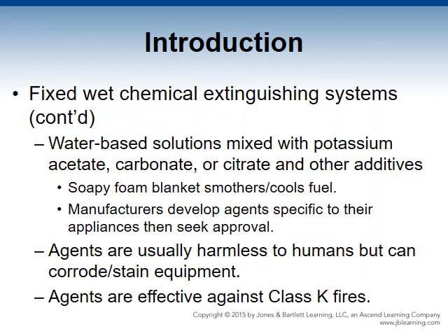Wet chemical extinguishing agents are proprietary water-based solutions mixed with potassium acetate, potassium carbonate, potassium citrate, and sometimes a mixture of these and other additives. The solution is the medium for the agent to flow onto the hazard. The agent reacts with cooking oils and forms a soapy foam blanket that comes between the oxygen and the fuel. This reaction is called saponification. It essentially smothers and kills the fuel, preventing reignition.